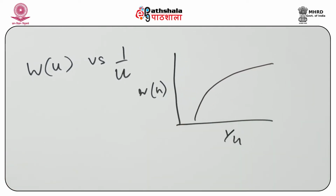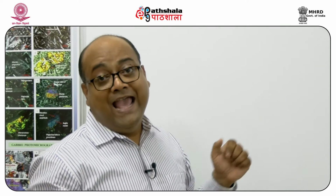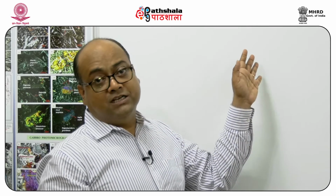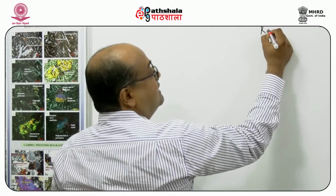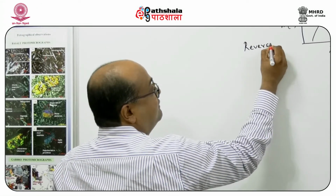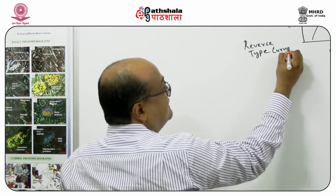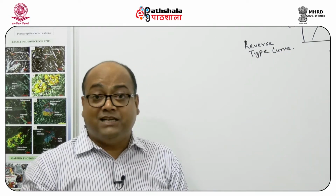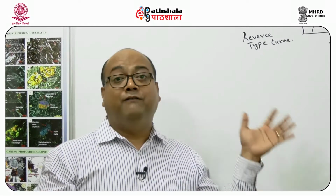The shape of the curve represents almost the depression of a water table, and this curve is a standard curve found in any book of hydrogeology. This is known as the reverse type curve, and it is used for the graphical solution of the Theis equation or the Theis formula.